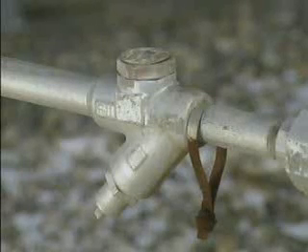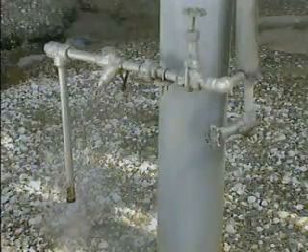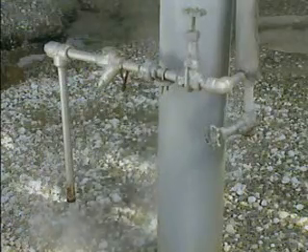Different traps have different discharge cycle rates. Disc traps, for example, are designed to discharge intermittently, so a continuous discharge could indicate serious problems. Float and thermostatic traps, on the other hand, are designed to discharge condensate continuously, as long as there's a constant flow of condensate into the trap.